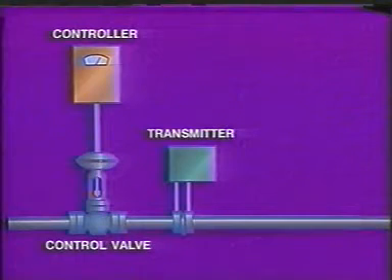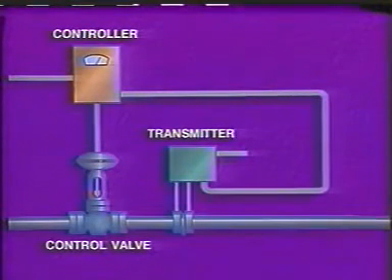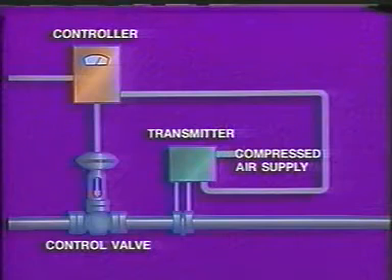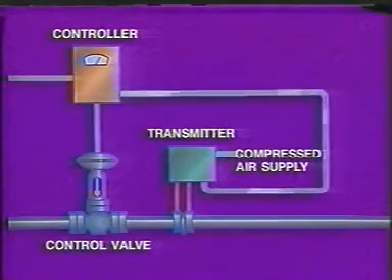Suppose we connect the parts of a control loop with pneumatic tubing. Assume our control loop controls flow, although it could be any variable. At the transmitter, compressed air at a constant pressure is continuously fed into an instrument supply air line. The flow information the transmitter receives through the tubing determines how much of the supply air is allowed to pass through the outlet line to the controller. If the flow increases, so does the air pressure passing into the outlet line.